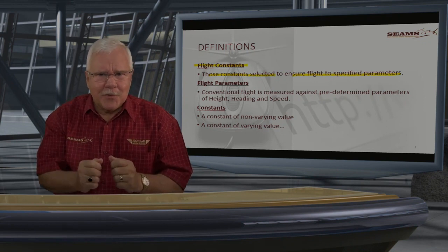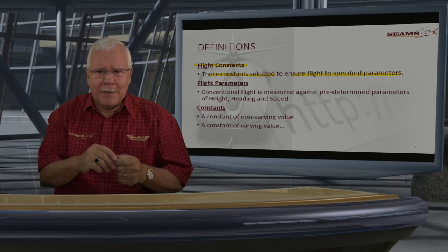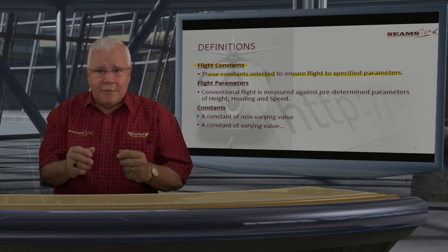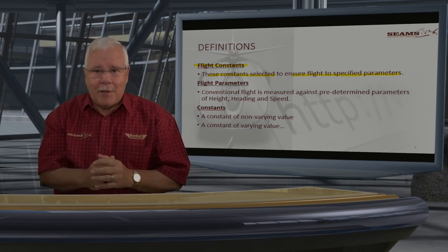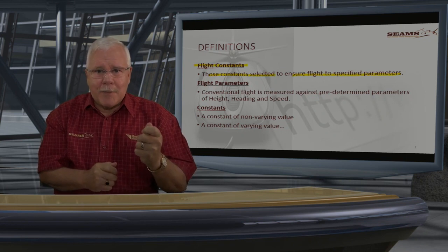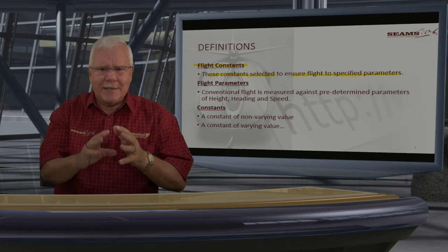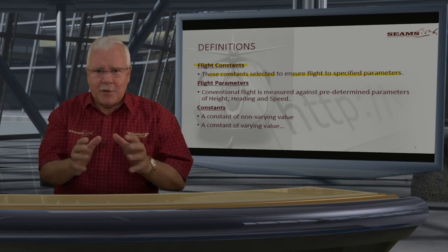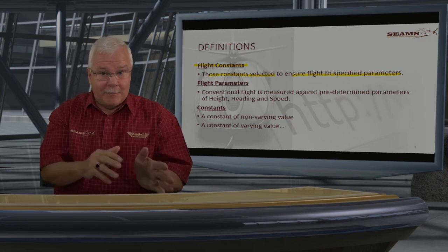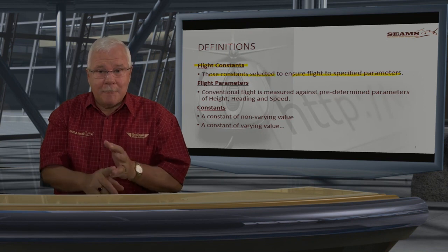Such as, for instance, cruise power. If you put cruise power in straight and level, the speed you get is the speed you get. You don't control your cruise power. You put cruising power and the resultant speed can change because of weight and density altitude and such a lot of stuff. I'm talking airspeed now, not ground speed. All right, speed. That's the one thing.